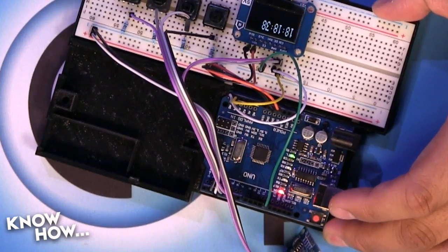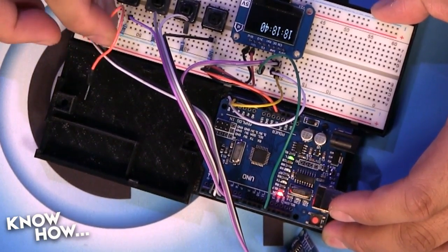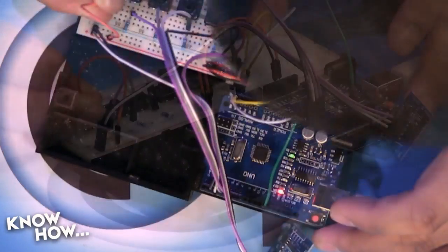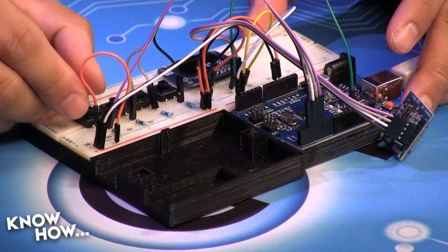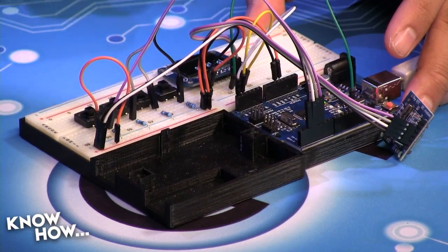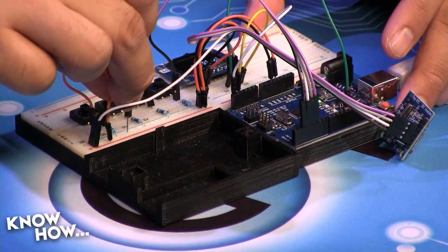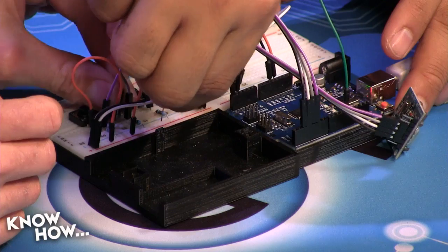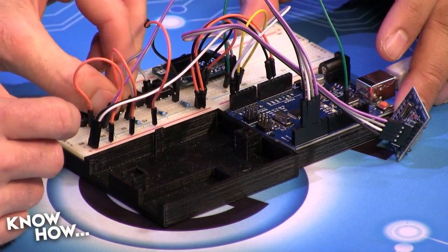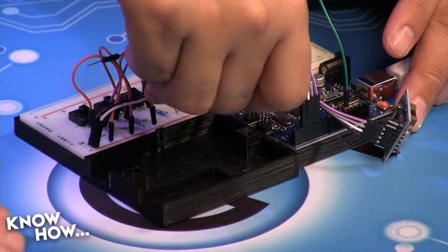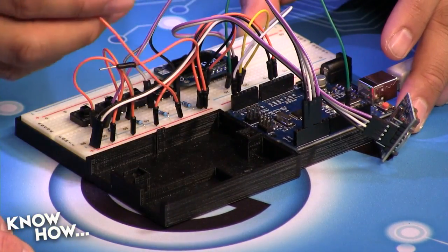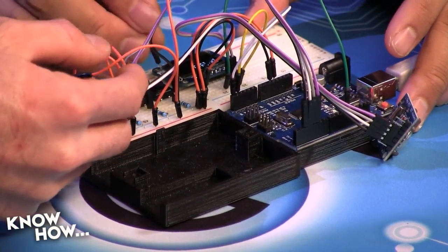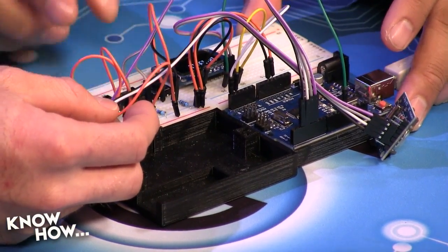Now I need to pull 5 volts to each one of those switches, so I'm going to pull from my 5-volt lead down into the switch. Can you make sure I'm plugging that in right? Yeah, sure. It has to be on the same rail as the actual pin for the switch. Yeah, you're good. You want me to plug in the rest of them? You do that one, and you do this one too. We're just taking power from the Arduino off of that breadboard rail, and making little circuits for the buttons. You do that one, and I'll do this one. Teamwork.